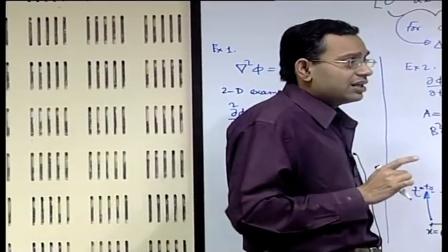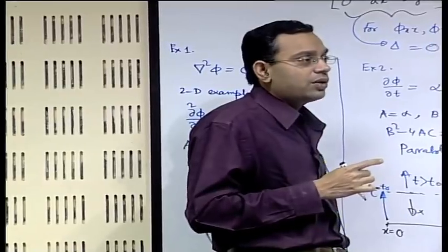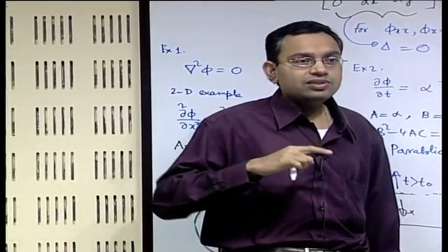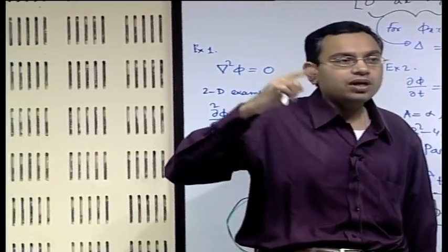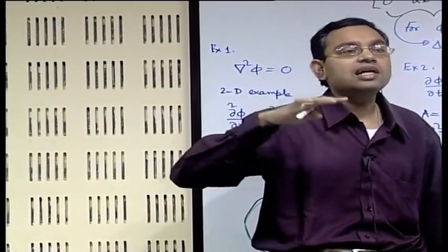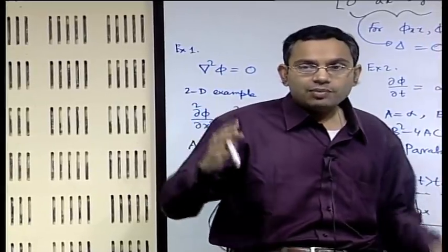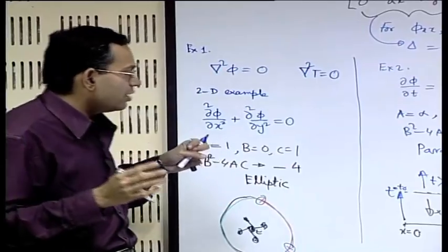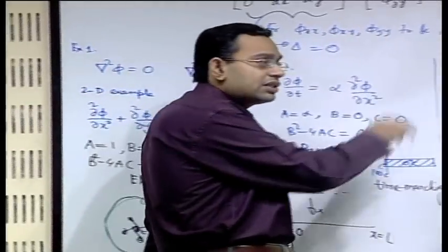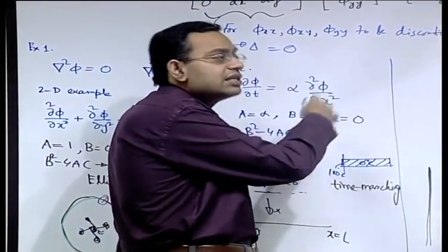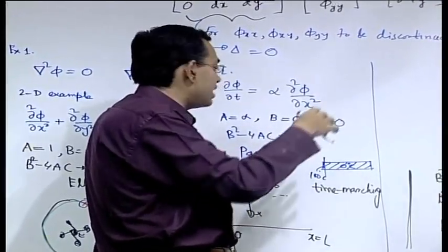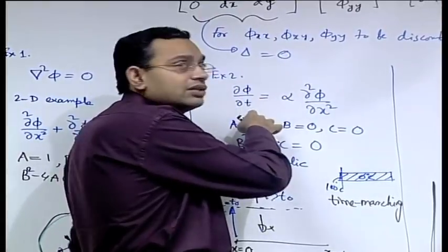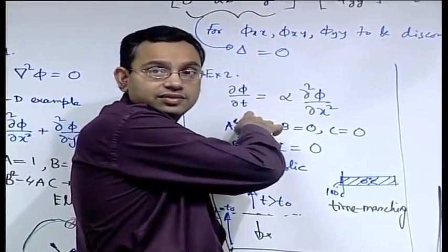Consider a heat conduction problem where time tends to infinity. There are many problems which at large times reach a steady state. There may be a transience over the initial period of time, but if you allow the system to evolve with time, it can attain a steady state. When it attains a steady state there is no more a derivative of temperature with respect to time; that ceases.